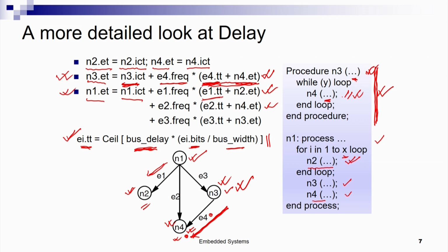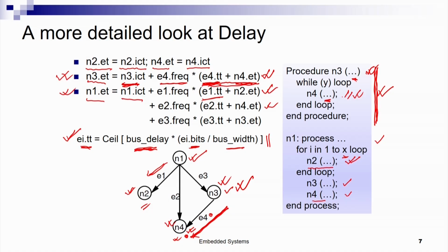It could be that you design one chip and put all the hardware functionalities into the same chip. So, hardware to hardware communication or transmission cost could be very low. Software to software transmission cost could also be low, because the programs are executing on the same general purpose processor, let us say. However, hardware to software transmission cost could be high, because these are on two separate processors.